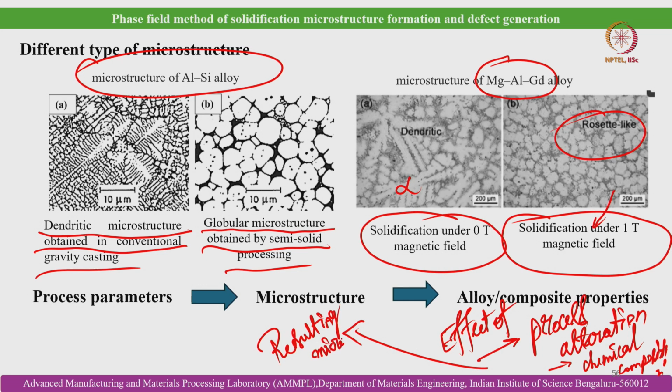One can predict this by developing an accurate phase field model, and thereby we can estimate whether the desired microstructure is achieving the desired quality characteristics in terms of size, shape and morphology of the grains, and thereby we can tune the process conditions and process variables. So, all those things are possible. This is the importance of the mesoscopic phase field model for solidification microstructure prediction.